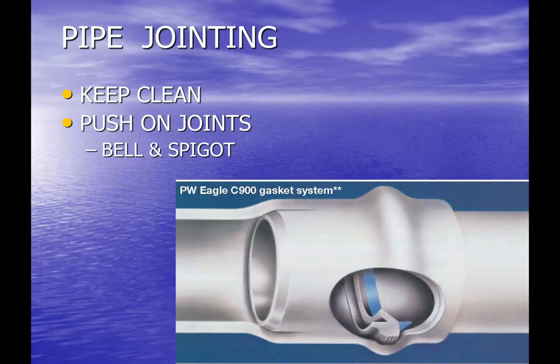This is the same picture we saw in the pipeline installation. It does a good job of, again, showing some of those same components. You see this beveled end. You see the gasket, which is what provides that seal. So in the event that we don't have some of these, for example, we cut pipe in the field, then we're going to have to use a saw or something to create that beveled end.